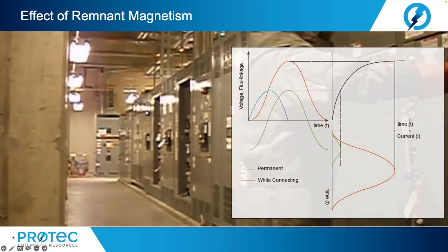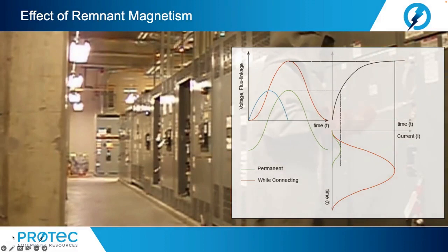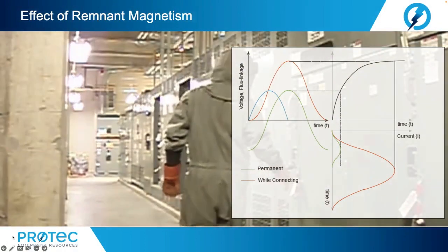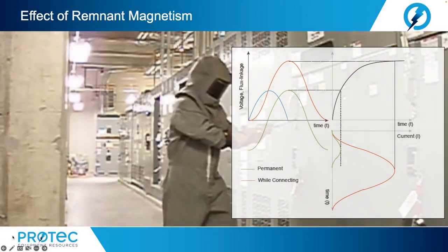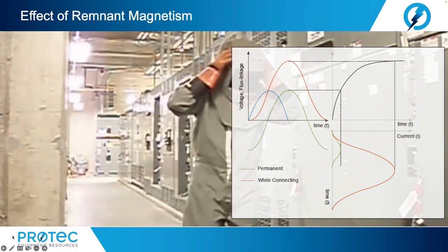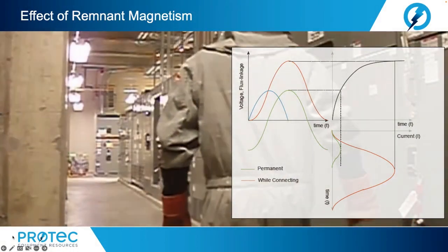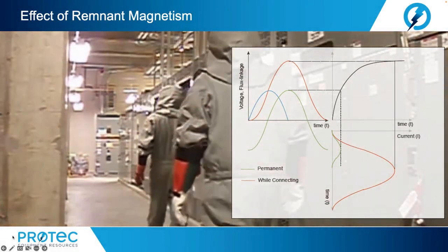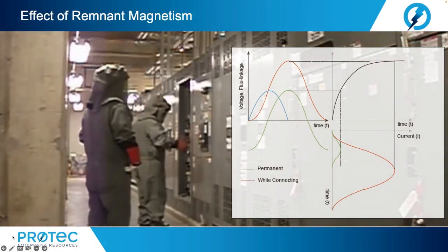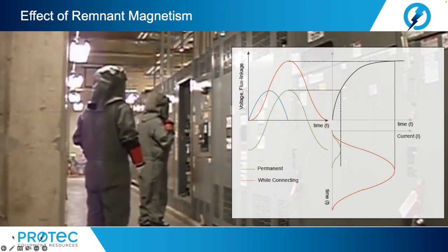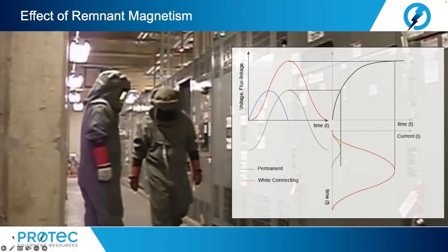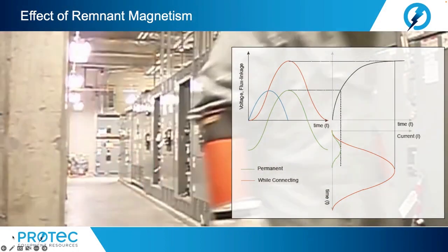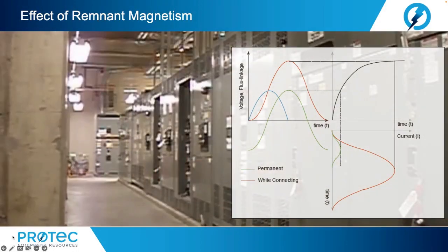But practically, it is not possible to have flux at the instant of switching on the supply of the transformer. This is because there will be no flux linked to the core prior to switching on the supply. The steady state value of flux will only be reached after a finite time, depending upon how fast the circuit can take energy. This is because the rate of energy transfer to a circuit cannot be infinity. So, the flux wave will be initiated from the same origin as the voltage waveform at the time of switching on the transformer.